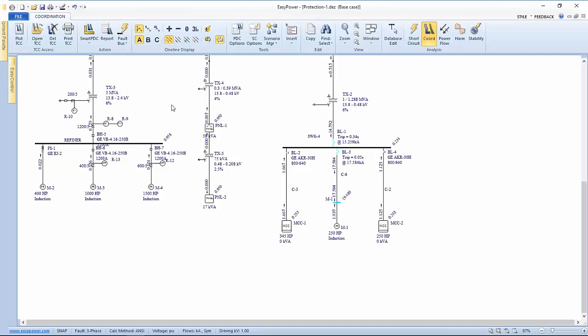And during the initial half cycle, which is what we're looking at, some 22 amps is contributed from this motor, some 100 amps is contributed from here. But the point is, there's a lot of impact on the system for this relatively benign fault, and it will last until we're able to clear the fault.